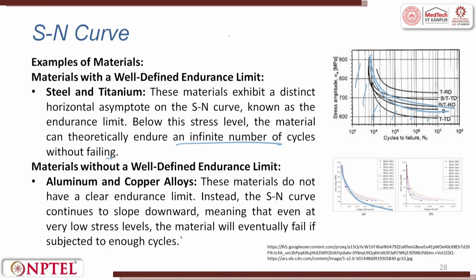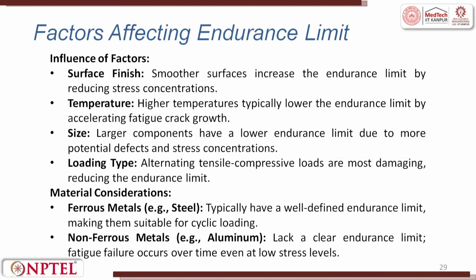In cars, we use an aluminum body, where there is not much of endurance involved. It is static, there is not much of moving. That is why we use aluminum frames. Copper alloys are the other materials that do not have a very well distinct endurance limit. That means you cannot use them for cyclic load.